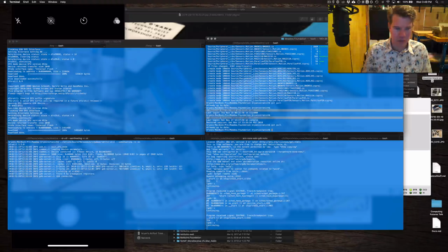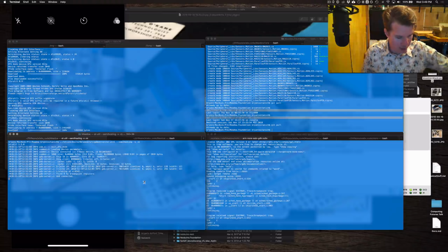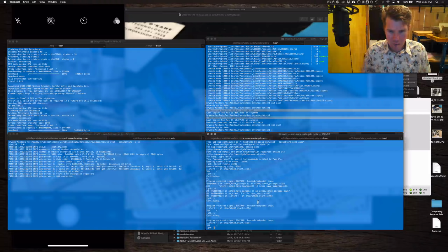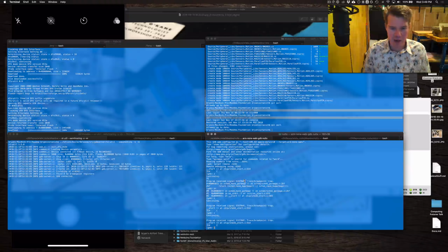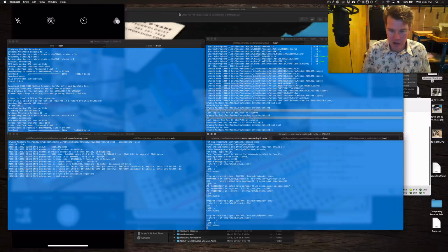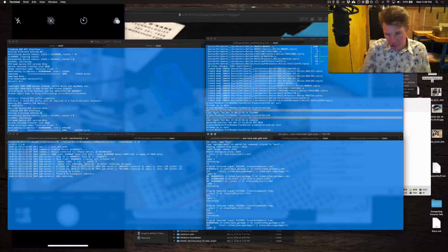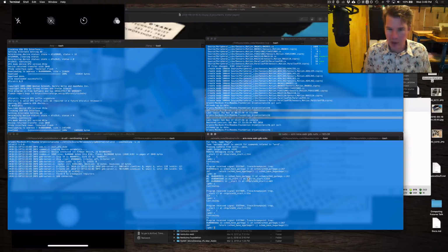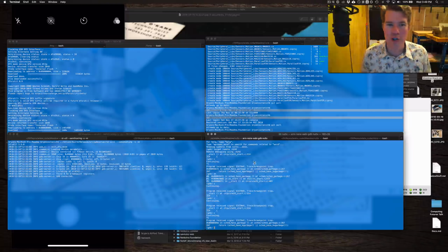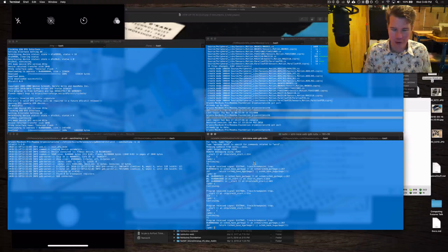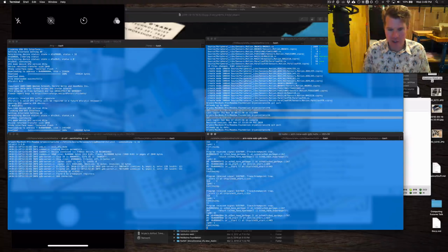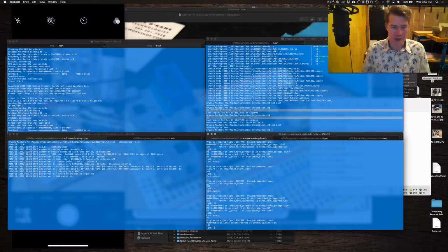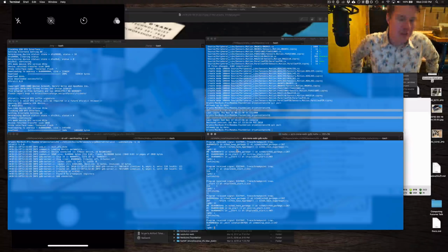And this is really interesting. When the device is running, over JTAG we have this debugging session, and we can connect to it and debug in the terminal. So here is actually a debugging session. Imagine this is the terminal version of hitting a breakpoint in Visual Studio. You have things like backtrace, you can see your stack, and you can continue, and do things like that. There's some real magic here to make this happen.